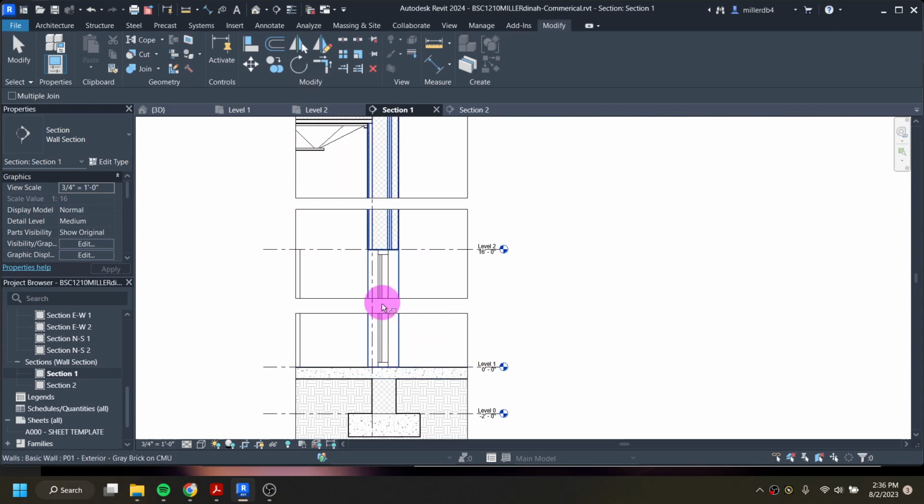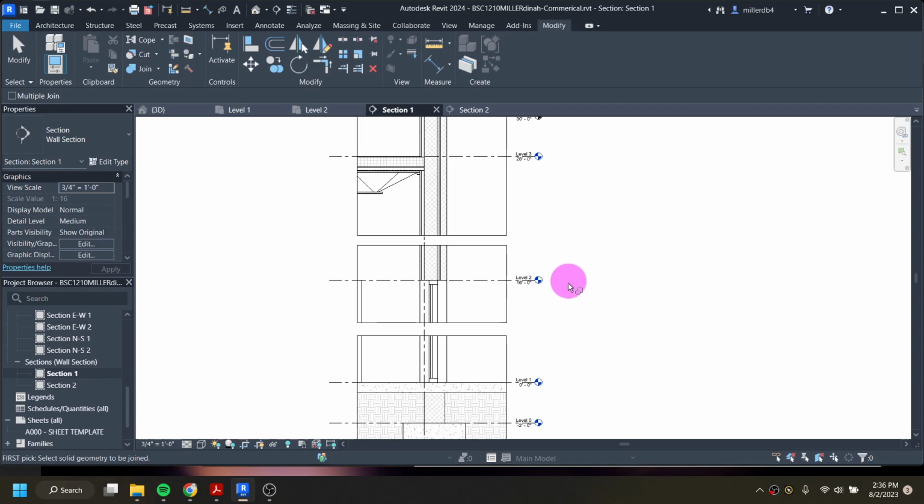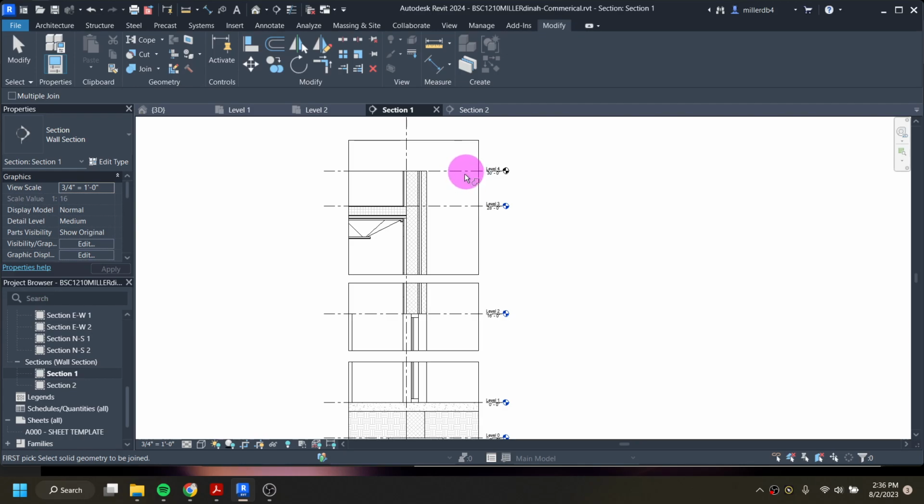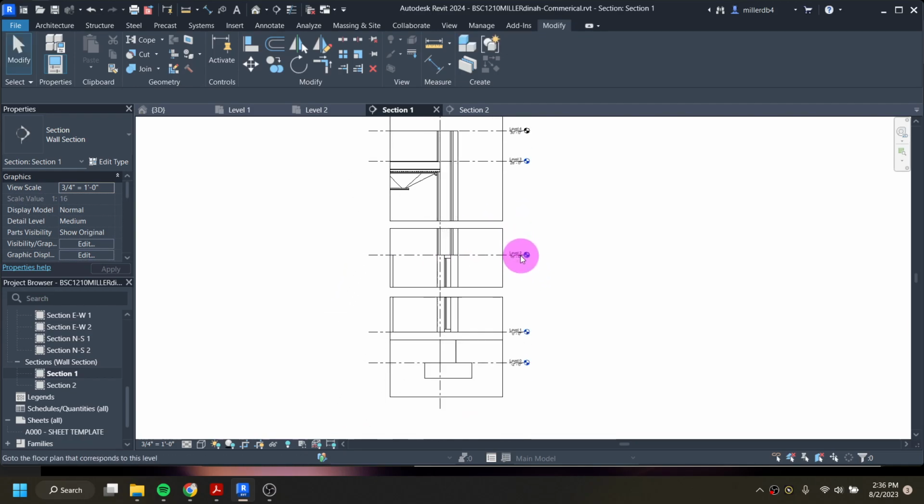But in this drawing, we're not really going to add a lot more detail to it. That's going to be our detail wall section, where we're going to add in tremendous amounts of detail to the drawing. We will also leave our level 4 here. We won't have to erase it within this one. And so at this point, this drawing is ready to go with one thing of hiding our crop region to finalize it to get ready to print.